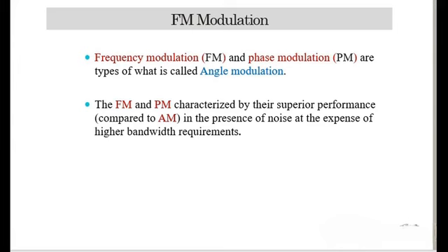The bandwidth of FM: the modulation index is mostly over one, and it usually requires a high bandwidth, at a range of 200 kHz. FM operates in the very high frequency range, normally between 88 to 108 MHz. Deviation: maximum deviation and frequency. The deviation ratio is equal to maximum deviation divided by maximum modulating frequency.